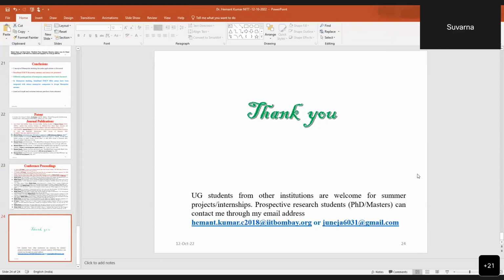Yeah, thank you. Sir, the session was really nice, and I just want to ask, maybe that question is very basic, but as I'm working in system on package, what other substrates can we use to implement this kind of antennas, and which parameters? I do understand that dielectric constant and loss tangent are very important parameters, but other than this, which parameters do we have to concentrate on if we are going for this kind of design?